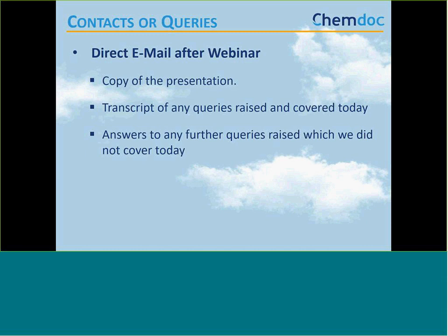So in the food industry, for example, your toxic chemicals need to be secured very much away so that there's never any danger that they can come in contact with foodstuffs, etc. But you also need to consider segregation from the point of view of not mixing acids and bases, etc. A common mistake we see with storage, we've often gone into places and you find chemicals are stored in alphabetical order. They're very easy to find, but it doesn't make good storage. You'll always have a couple of hazards that are together that should not be together.